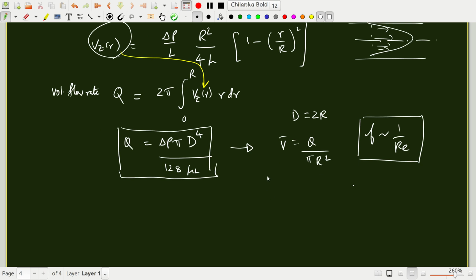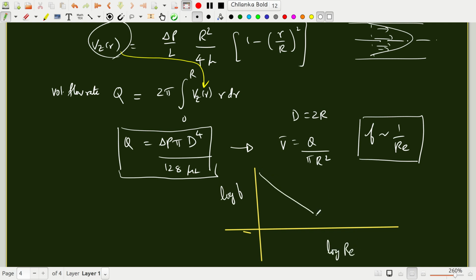But even though these are rigorous solutions of the Navier-Stokes equations, you will find that they do not agree with whatever is being theoretically predicted. This is one of the main problems of fluid mechanics, in that you may use simplifying assumptions to get the laminar flow solution, and you will also be able to get some relation for quantities like friction factor, and that may agree with experiments up to some Reynolds number.